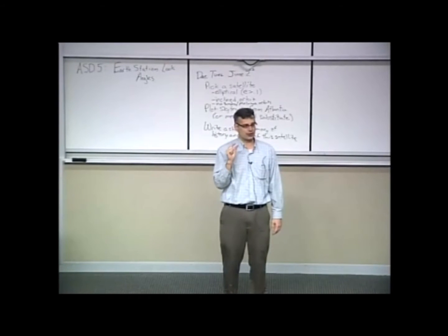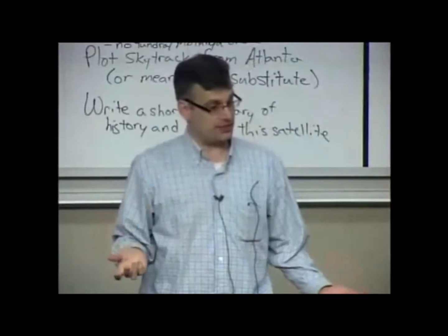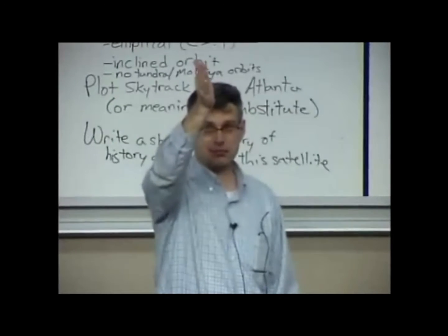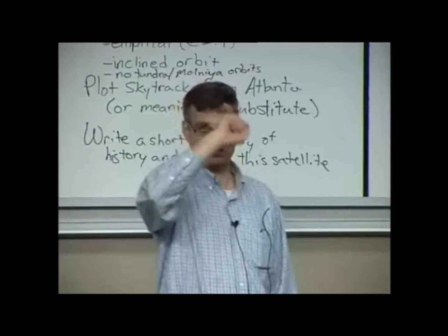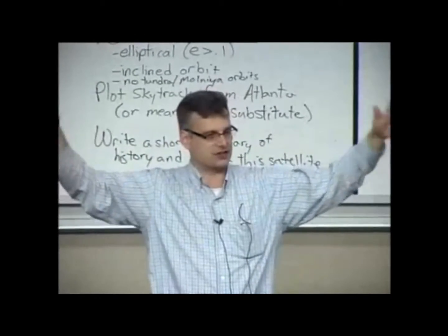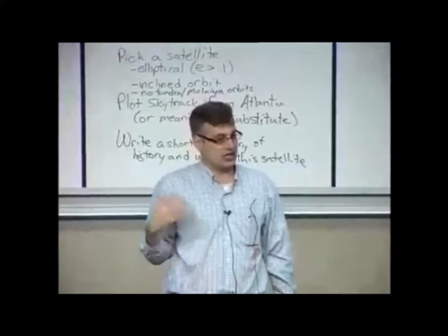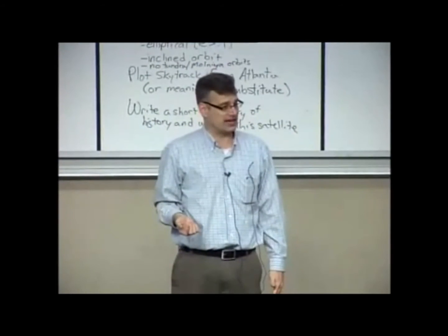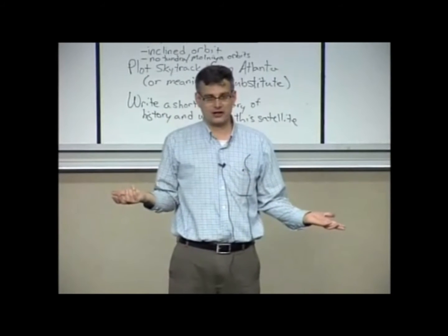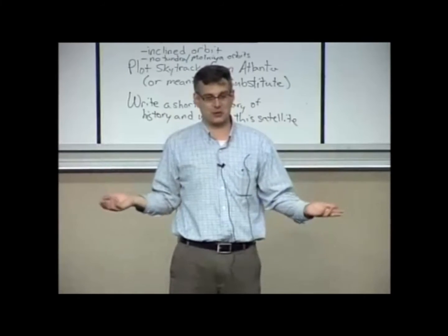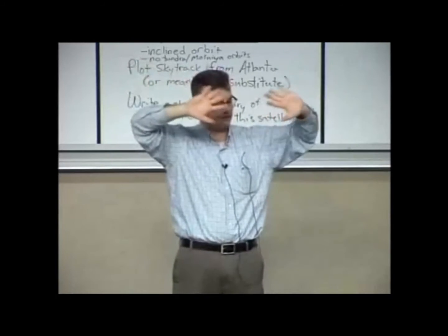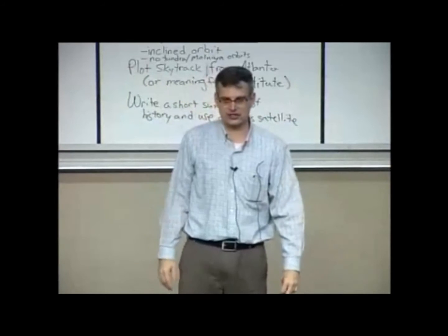But it also has a pencil-thin beam, which is good because when you dial it into a particular satellite up in the sky and point it, that means you'll get that satellite with a lot of gain, and you'll exclude everything else. Everything else will have a significant amount of attenuation, even other satellites that are using the exact same bands. So this is how you reuse frequency in space when you don't have the luxury of the cellular network of having buildings and trees doing all the hard work for you, blocking signals and filtering out from other regions of the cityscape.